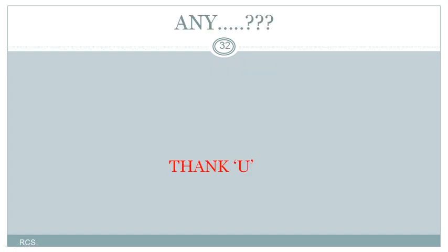Thank you. Let us just summarize the things we have discussed. We decided to design a one-way slab with simply supported ends. For that, we calculated the effective length, the effective depth, and the total load to be carried. Based on that, we found the total bending moment it has to resist, and the area of tension reinforcement provided, and whether it is suitable and safe against the codal provisions. We have checked deflection, shear, and development length also. So that's all for today's lecture. Thank you.